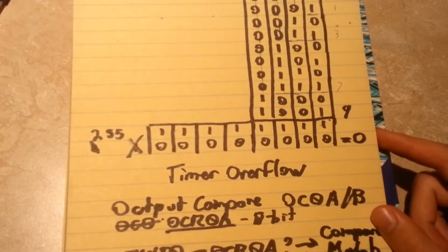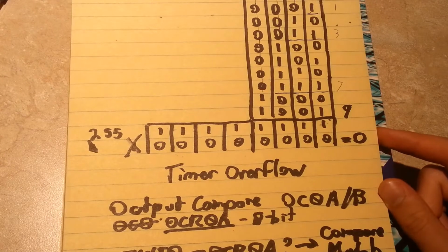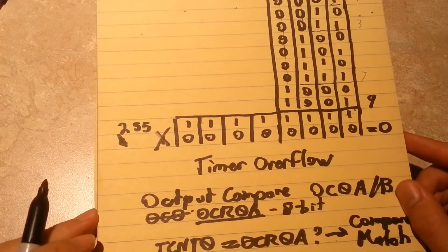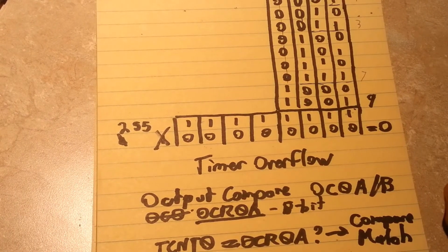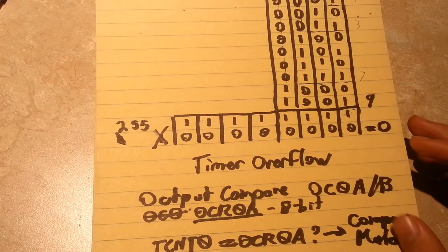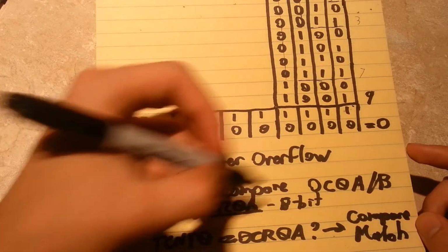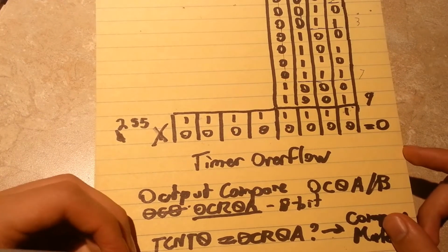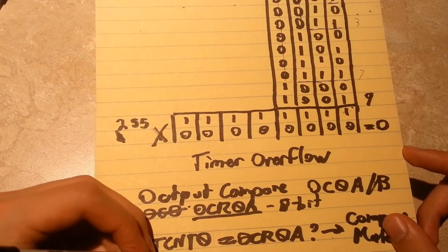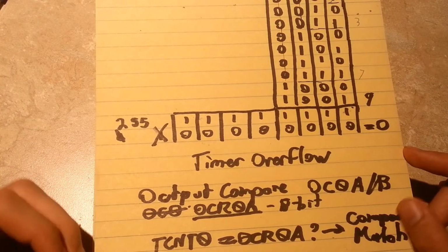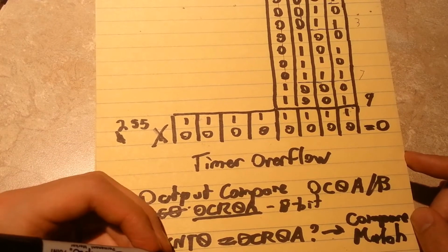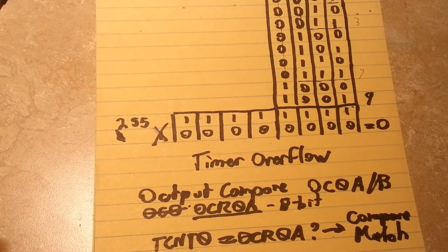Now that term sounds familiar from somewhere. Oh yes, it was in the data sheet. We were looking through the implementation of analogWrite, and that led us to a truth table which said that OC0A is cleared on compare match and set at bottom.